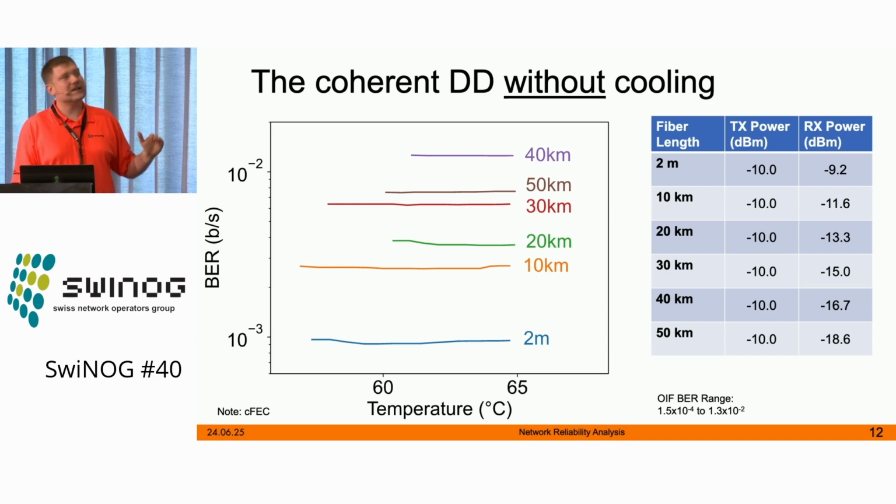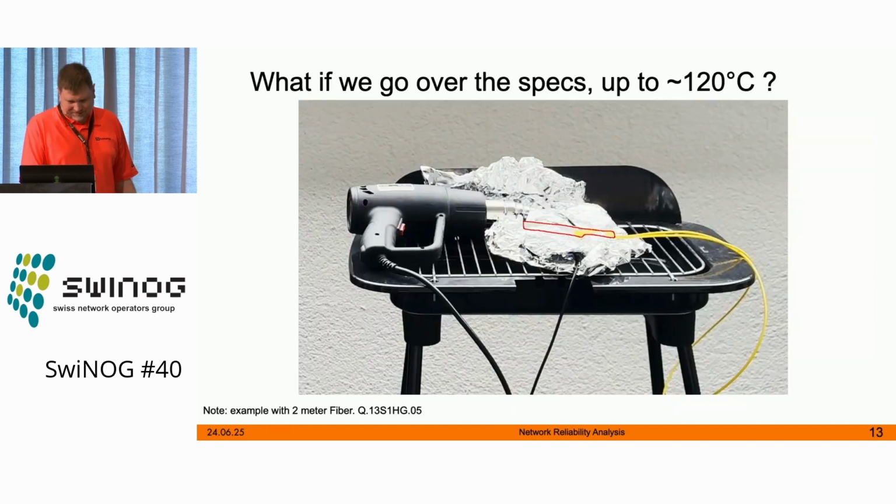If you use different fiber lengths, obviously you get different bit error rates. What is more interesting is the range, where we have 10 to the power of -2 and -3. That's a different specification, because the amount of parameters is like with control circuits. If you have more parameters, you have more ways to correct your signal. And here, the coherent transceiver is a little bit more tolerant. That's the reason why coherent transceivers, at least this low power one, can also deal with higher distances. Here, the attenuation was not required, and that's a big advantage.